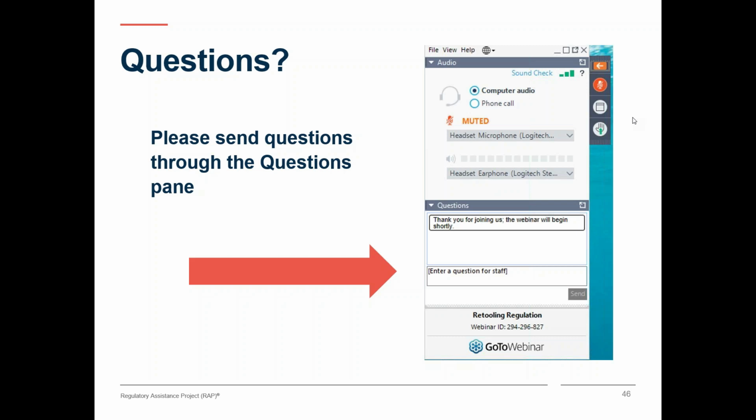And the first question, about how you deal with the fact that things are changing, that maybe you're going from a midday peak to an evening peak and a very low morning net load as solar comes online, or perhaps a different kind of shape as your wind penetration rises. To deal with that, you might want to look at the costs, both for cost of service and for rate design, using expected load shapes over the next several years, at least for the years in which you expect the rates to be in effect.